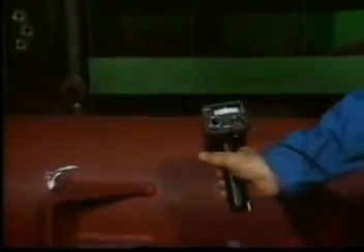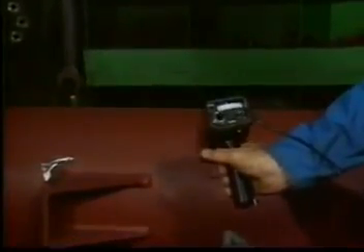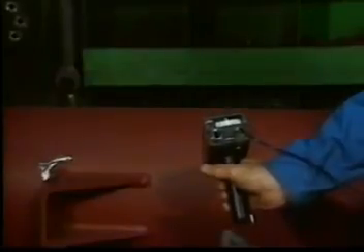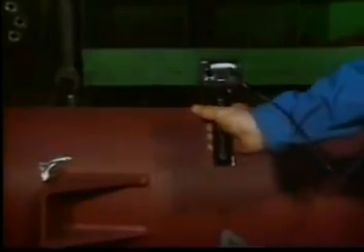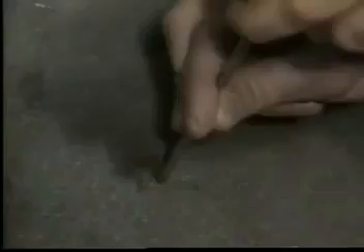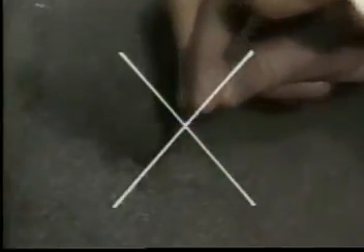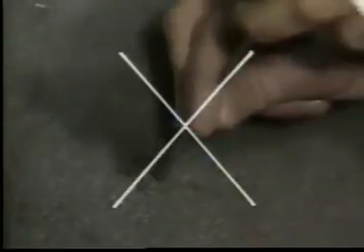If you're unsure about what you're hearing, compare the sounds with those of other heat exchangers in a similar area with similar load factors. If there is insulation around the heat exchanger, make plug holes and test each time at these sites. Never use the contact probe to create a hole. The pressure will damage the transducer.